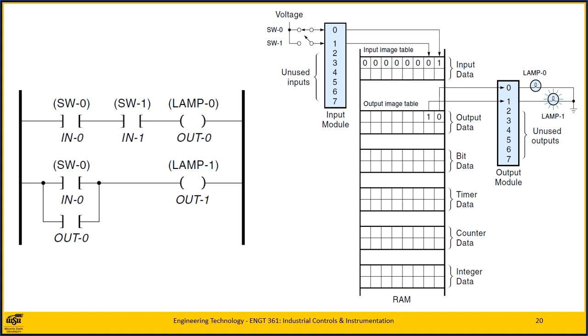A final observation of the PLC hardware operation is that, for all practical purposes, it can do many independent control operations at the same time. We have been conditioned to think of a computer as being able to do only one thing at a time, albeit very rapidly. And as we have seen, the PLC does not execute its program one rung at a time. However, each rung is a separate circuit, and each control application, as far as the PLC is concerned, is only a set of rungs. Therefore, you can have one PLC running 3 different control applications at the same time.